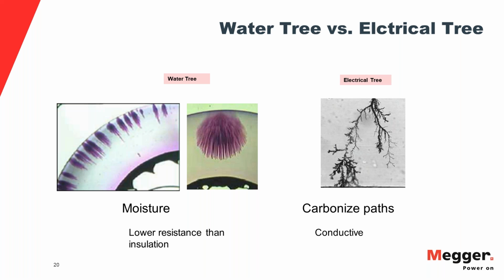It's also able to detect certain types of weak spots in the cable, such as something like water trees. That's more of a resistive type of fault than a capacitive type of weak spot. But I can see Robert over here chomping at the bit to answer more.